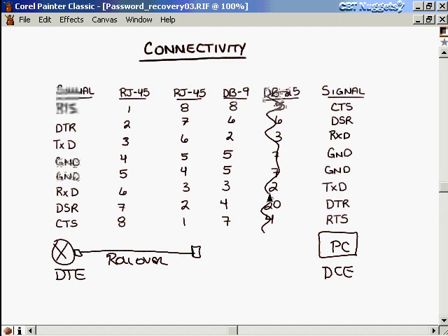All right, so with the DB9 connector, these are the pins associated with each of the signals. So what if we're using a DB25 connector? Let's do this. Let's mark out the DB9. And now you see here, 8 to 5, 7 to 6, 6 to 3. You won't have to know this on a daily basis, but it is very good to know for troubleshooting purposes, or if you have a myriad of connectors and you're not sure which one you're supposed to use, you can simply run the test or run signals through those connectors and make sure they come out in the correct pin.